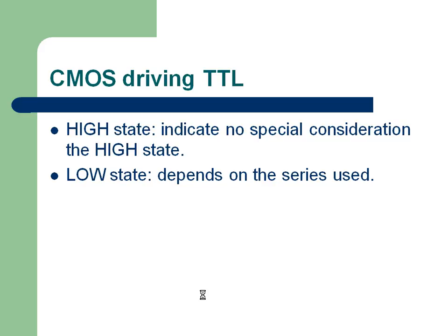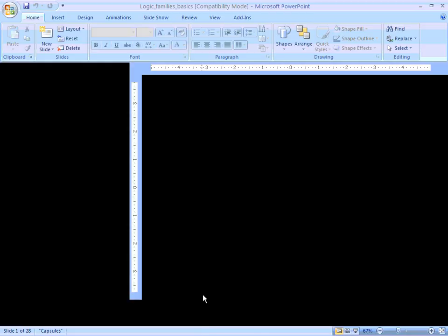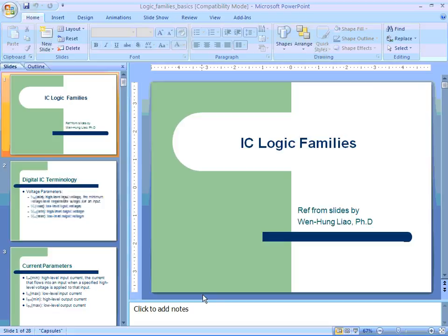Now, if you want to go in depth, why you are so concerned about low and high is, in the case of TTL, recollect that there is a base-emitter junction. So the emitter needs to be some 0.6 volts lower than the base to turn on. There it becomes a special problem. But for output high, it's not a special problem because it is already above the base limit. Even if it is a little above or fully above, it will still be considered a 1. That's the reason we are talking about this. Anyhow, this much is enough for understanding how these logic families work.